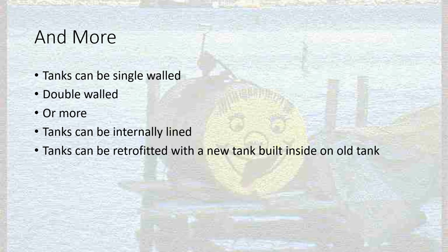Compartmentalized means that you have a tank that they've split into sections. So they put some kind of wall or bulkhead in the tank so that it portions it out, so you have like a 20,000 gallon tank, and one end of it is going to be 12,000, the other end is going to be 8,000, and you can store 2 different products in that same tank. And you'll see that a lot with the delivery drivers. Their tanks are usually compartmentalized like that.